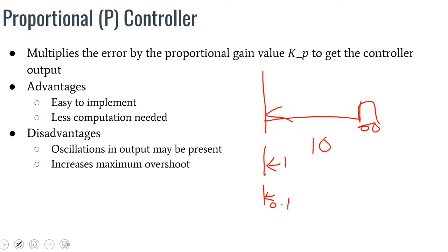By the nature of physics and how things work, it cannot suddenly stop at that point, and it may go past this point and stop after a bit. Then, having stopped missing the point, it has to come back again, so it will try to reverse. Again it will use proportional control, and again it will come back, maybe not stopping there, coming a bit further. So it will have to move back and forth.